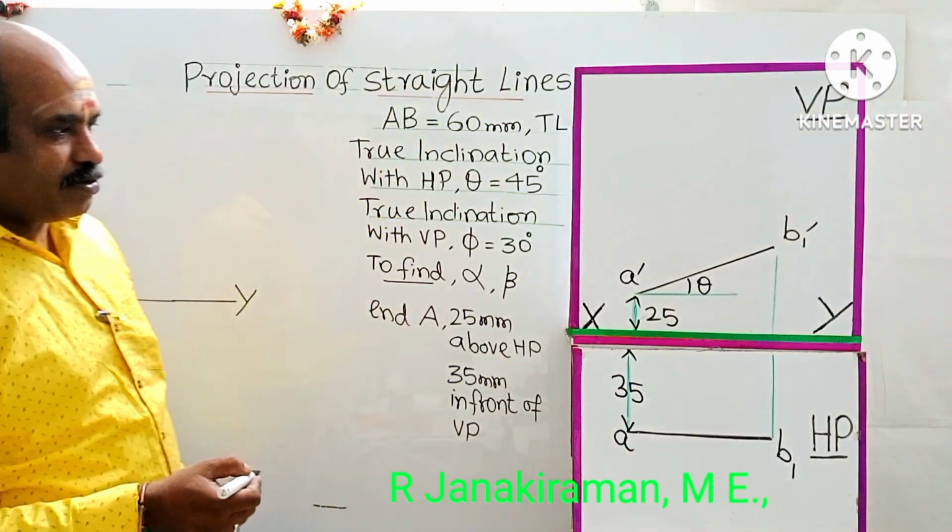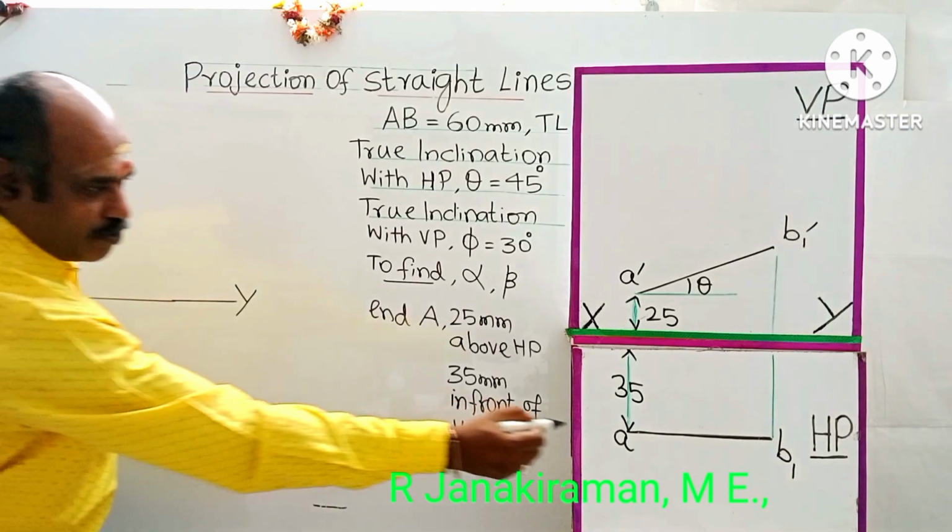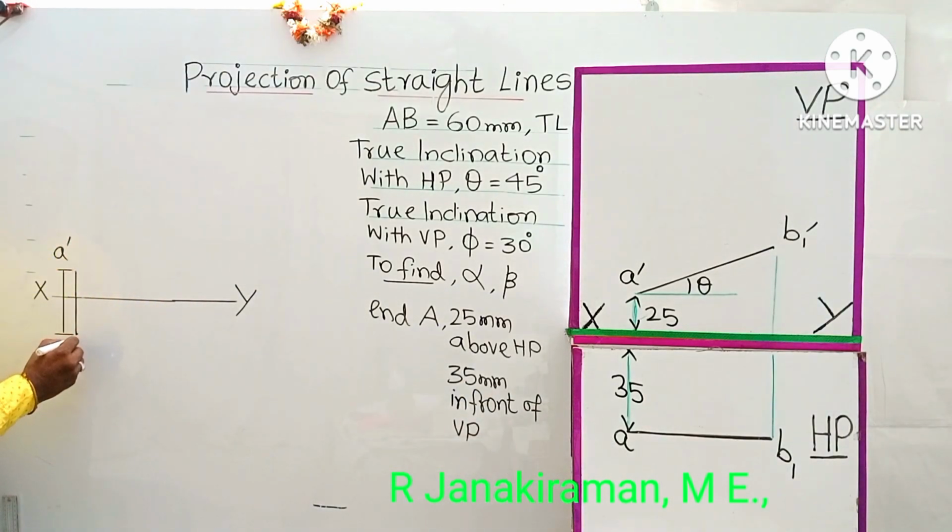This is not the final top view. This distance is dimensioned. Draw an extension line from point A dash. Draw a dimension line. And the in front distance comes below. Below, this distance is 35 mm from the located point A dash. This point corresponds to the top view called A. Understand? So let us dimension, put the two narrow arrowheads, shade the arrowheads, and write the distance.